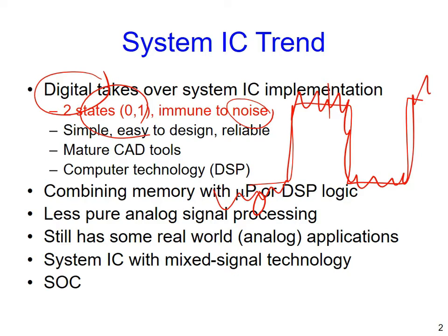Why? Because in digital circuit, they have the so-called threshold voltage. Yes, we also have threshold voltage, but that is totally different. Usually, the threshold voltage for digital circuit is in the middle of your power rails, and it means 50% of the VDD. Above the threshold voltage, it will always be 1. Below it, it will always be 0. So in digital domain, we have the so-called data regeneration, 资料重生.